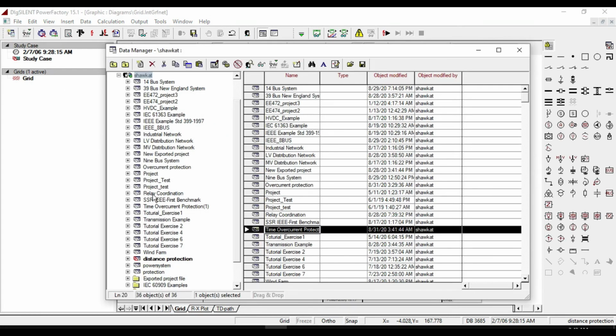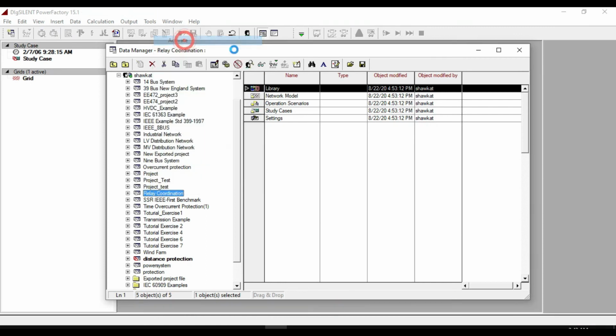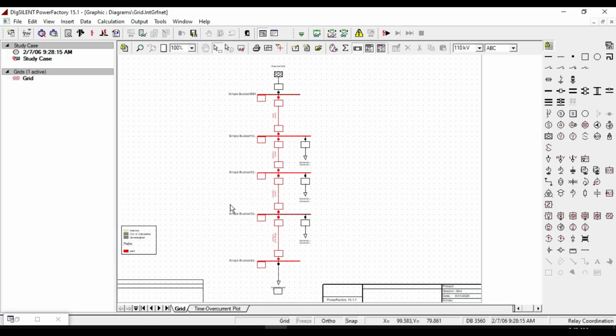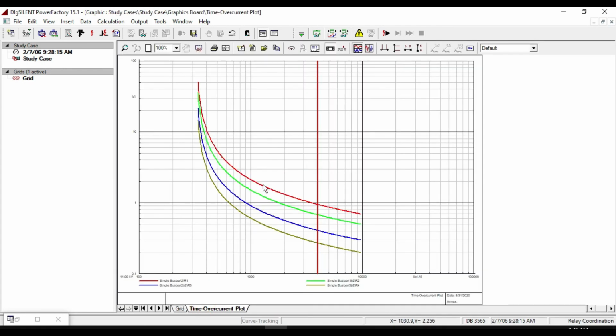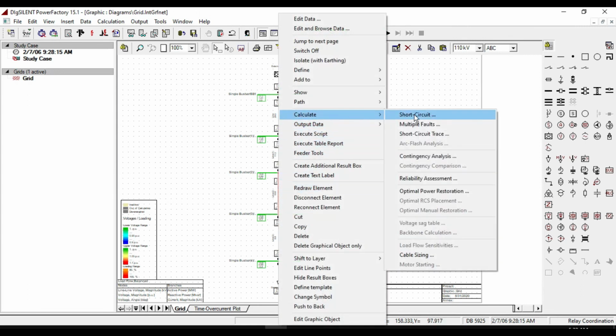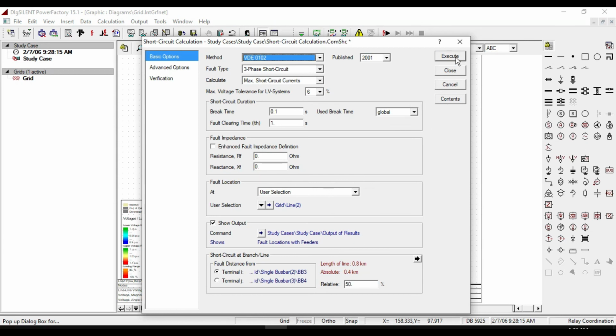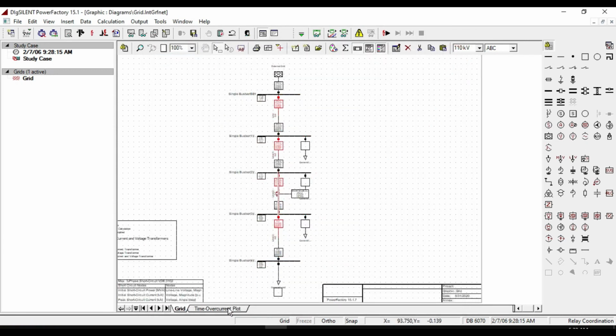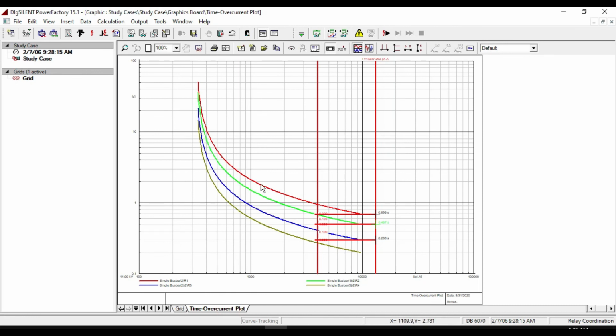We have discussed overcurrent relays, so why should we go for distance protection relays instead of overcurrent protection relays? For short transmission lines, an overcurrent relay is good enough for protection when directly connected to a generator. But in a complex power system, not all transmission lines are necessarily connected directly to generators. So in this case, overcurrent protection relays cannot provide proper protection.